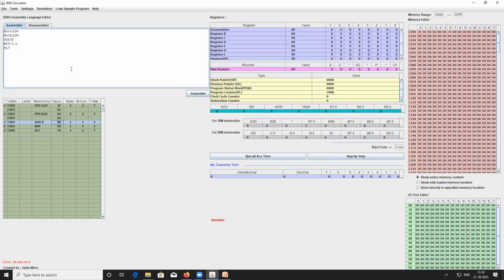In the 8085 kit, what do we have to do? We don't write the program as written here. You have to enter the hex code 3E 03 06 02 and so on into your kit and then execute the program. After execution, you will get the output 05 stored in the register. There is a register button in the 8085 kit, and that will show the accumulator contains 05.